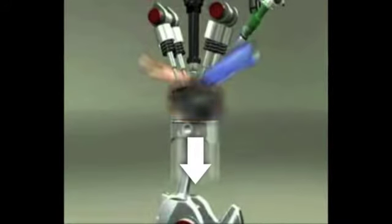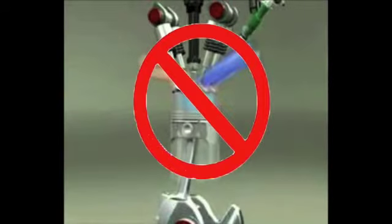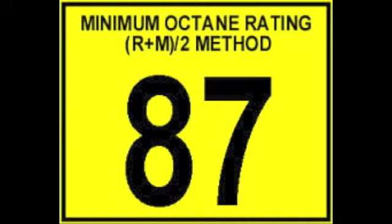Knocking occurs because when the fuel is compressed inside the cylinder, it heats up, and if it's compressed too much, then it can actually self-ignite, causing the piston to move back down before it's supposed to. Knocking can actually cause damage within the engine of your car. Because of knocking, this is why when you're at a fuel pump, you should always buy the gas with the octane rating designed for your car.